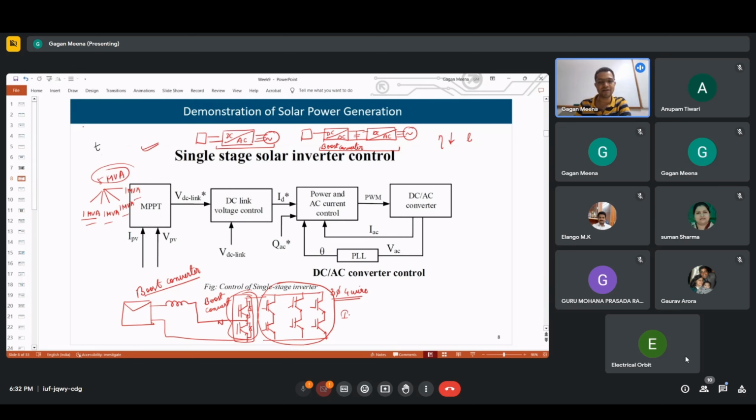So you are saying B is not correct. So these are interlinking converters. A single stage three-phase inverter is an interlinking converter. These are bidirectional and they work on this principle: equalizing DC side per unit voltage and AC side per unit frequency. And back-to-back converters are